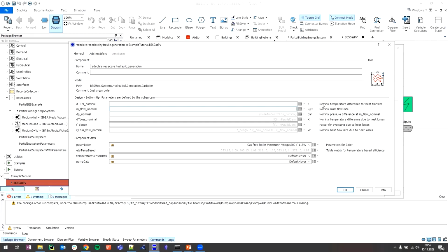If you simulate the heat pump model, there is a recommendation in the European norm on which temperature difference to use at which temperature demand level. So this is automatically calculated for you. I would just say, okay, it's 10 kelvins. I don't know if it's a good assumption, I guess so. So anybody disagrees, just state it.